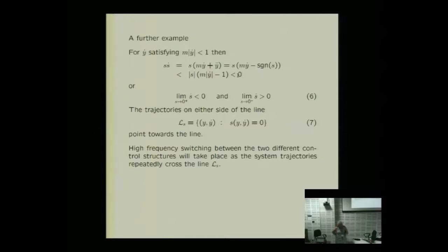We have to realize that high frequency switching for some things is fine. If I've got some power electronics, it can be switching at really high frequency, it's going to be fine. You see a lot of the literature using the controller through power electronics. Not a problem. Professor Utkin, the founding father, has done much work on control of those kinds of things for electrical machines and drives. So it's not that high frequency switching is not sensible for everything. Some things it's fine.